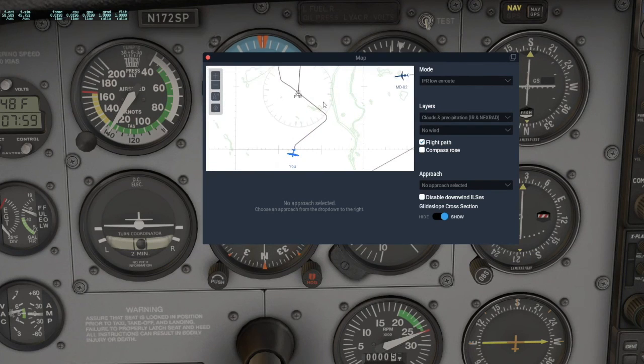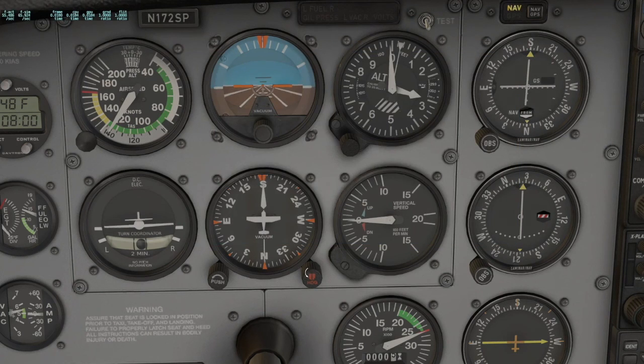Here we go. We were here flying in this direction. We were instructed by ATC to intercept 180 outbound, and we came at it with 45 degrees, as you can see. And then once we intercepted, now we are going in that direction, 180 radial outbound, away from the VOR. And as you're flying, you need to also keep an eye on the needle and adjust a little. If it goes a little bit to the left, you're going to head a little bit left until you bring it back into the center, and then you come back to the same heading that you selected, whether it's inbound or outbound. Okay, now you're flying, and let's do another exercise.